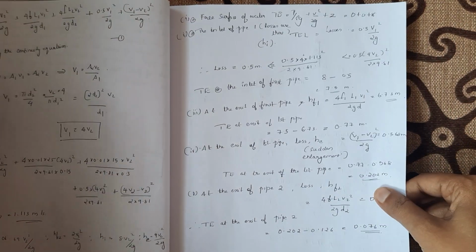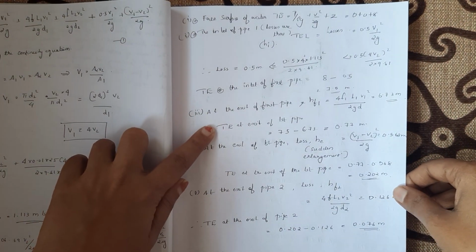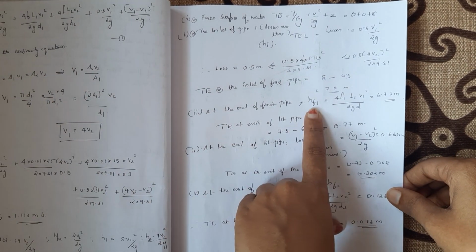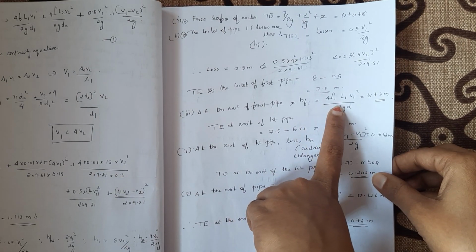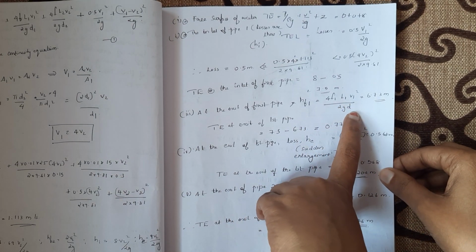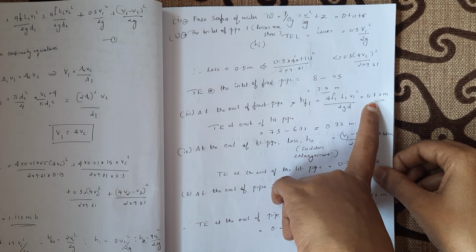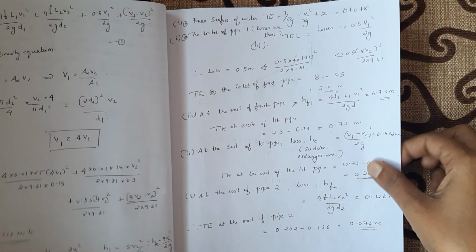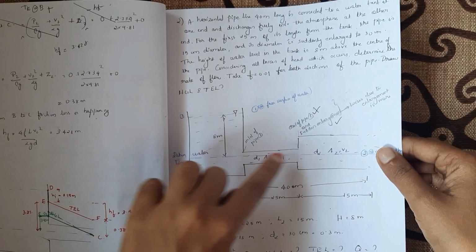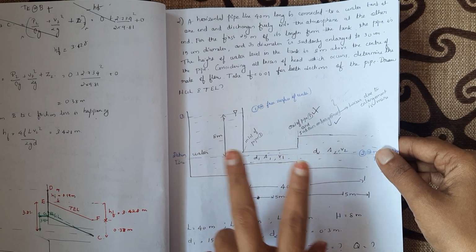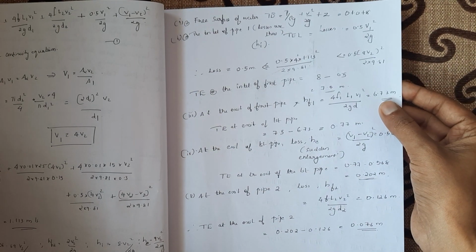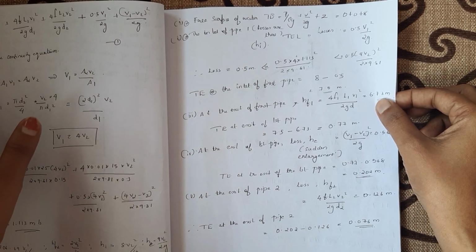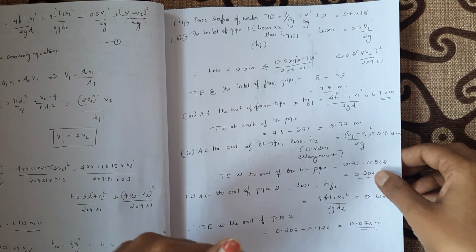And next is at the exit of the first pipe. We know that in the first pipe there is major frictional loss happening, isn't it? Therefore, hf1 is equal to 4 f1 L1 V1 square by 2gD. Substituting everything, we get hf1, the major frictional loss, as 6.73. So by the time the fluid has flowed from this inlet to this exit of the first pipe, this much head is lost. 6.73 meters has been lost due to the friction. So you need to mark that also. So we need to subtract that first, isn't it?